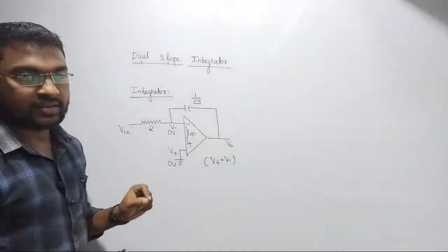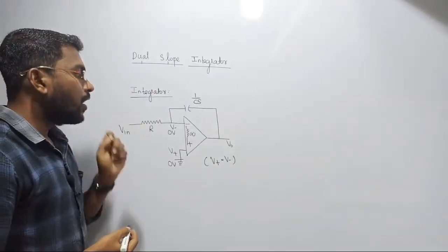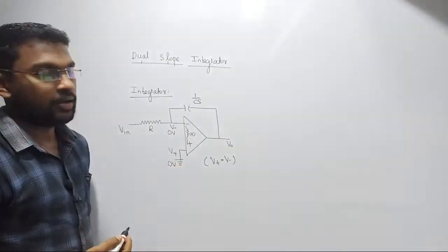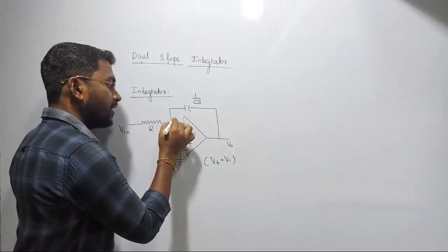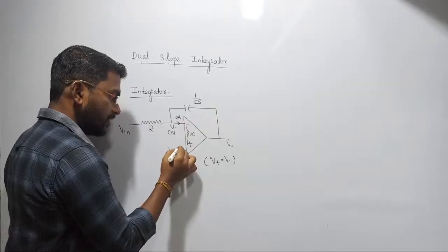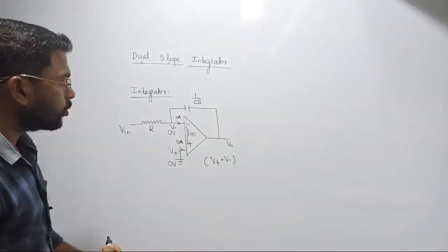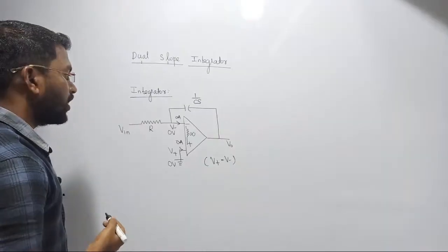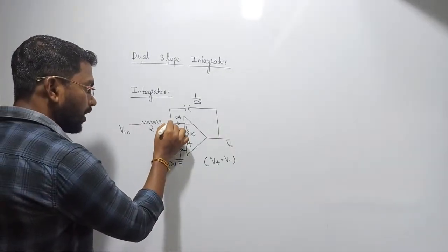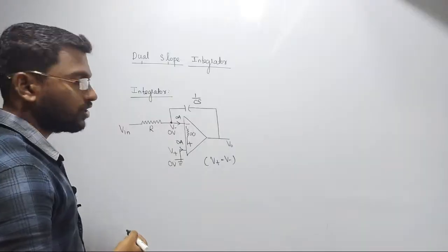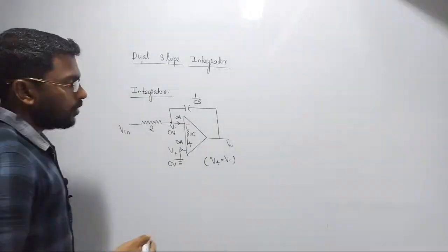The input internal resistance offered by the ideal operational amplifier is infinite, such that the current taken by these internal branches is always 0 ampere. There is no current entering the operational amplifier at both these terminals, right? Fine. So let us apply nodal analysis once again at this junction to obtain the solution for this given function. If you apply nodal, what will you get?